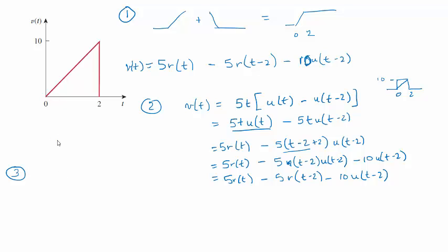You could multiply the ramp right here, which is r at t at 0, times a step function that goes the other way. So if you multiply these two together, this is 0 times that, and then this number times 1, and then back to 0 here, you will indeed get that sawtooth out.